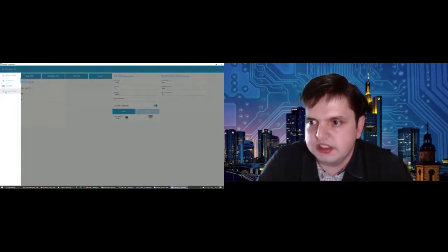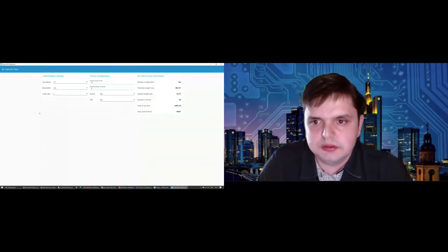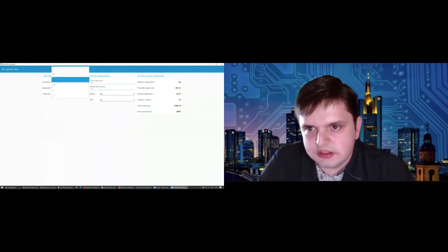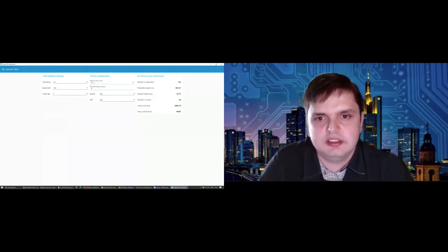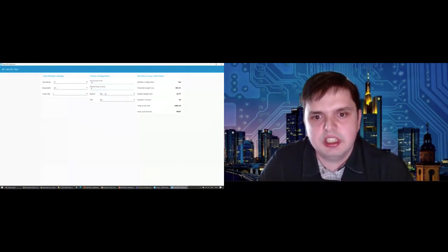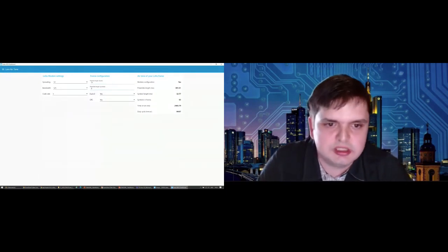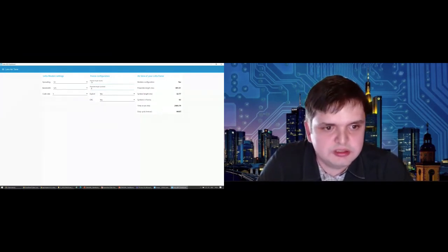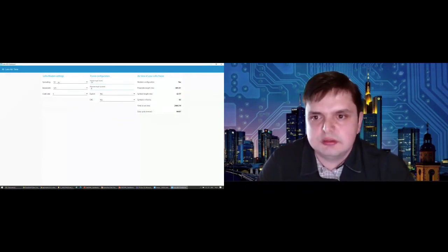And then there is the LoRa airtime, which is a theoretical part. If you want to know how much time on air your packet will take, you enter your parameters: spreading factor, bandwidth, how long the payload is, how long the preamble is, if the header is explicit or not, if CRC should be calculated or not, and it will calculate the time on air and the duty cycle, after what time you can transmit again.